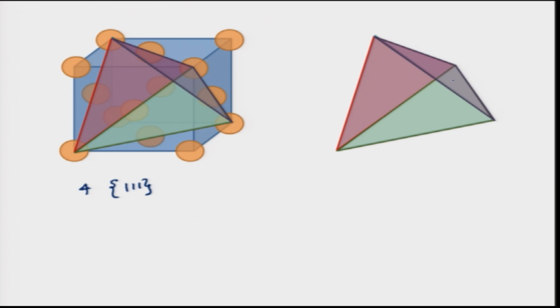So, even the directions, the edges, are also telling us something about the possible Burgers vector, the 110 direction, and we know that each 111 plane has 3 possible 110 directions, and thankfully for us each of these is a triangle. And all these 3 are representing 3 independent 110 directions.